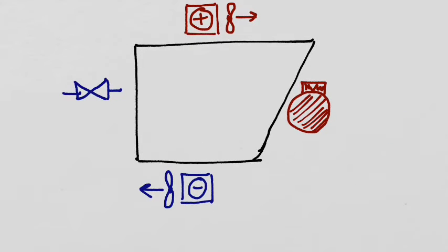The refrigerant cycle goes like this. At this point here, we have liquid refrigerant that is 100% liquid. It is injected by the metering device into the indoor coil, and there is flash of gas, and we bring the temperature down. Next, the refrigerant moves through the indoor coil, where it exchanges heat energy with the air that is drawn through the coil by the fan.